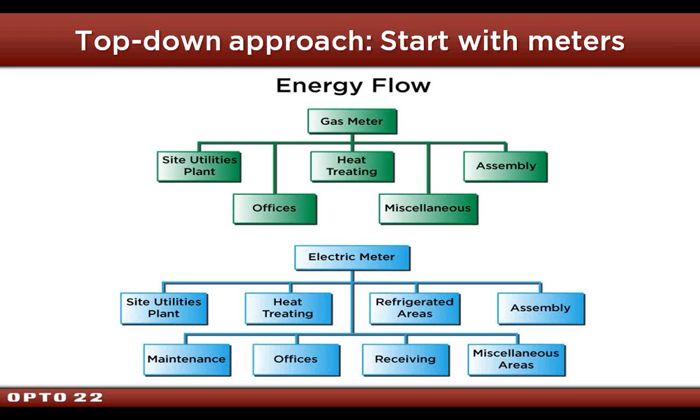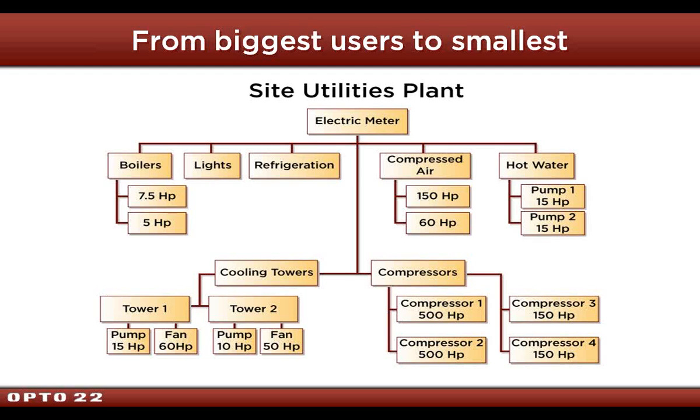But if you start with the main meters, you start with the main loads, the main pieces of equipment. Most industrial plants will have a boiler house, air compressors, chillers, and we're talking, we did gas, electric, steam, water, any utility that people are spending money on and want to manage, we did it. So you go in, you pick the points you want. If we had big motors, we had air compressor systems, and then you look at physically what it takes to tie into those. And we found a lot of really cheap ways to get a lot of data tying into points.